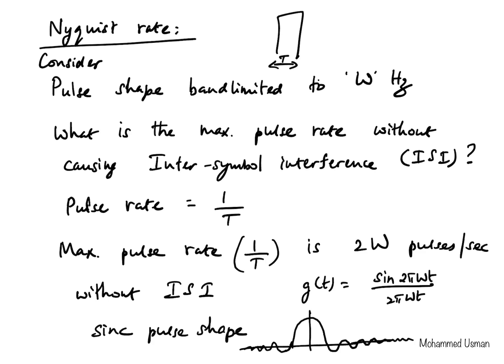So with such a pulse shape, we can have neighboring pulses arranged in such a way that when one pulse is going through its zero, another pulse is at its peak. So we can have the neighboring pulse going like this. When this pulse is zero, the neighboring pulse is at its maximum, and when this pulse is maximum, the neighboring pulse is zero.